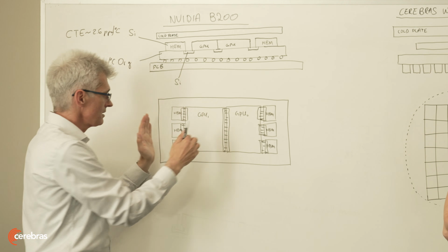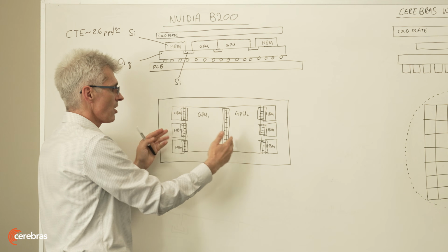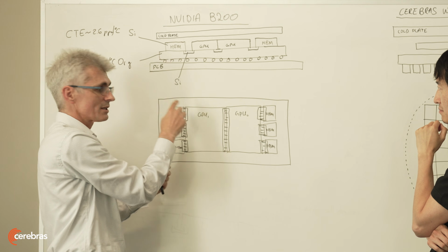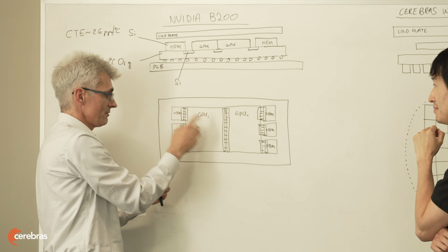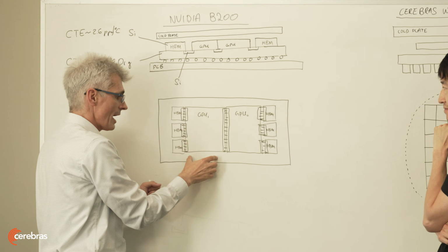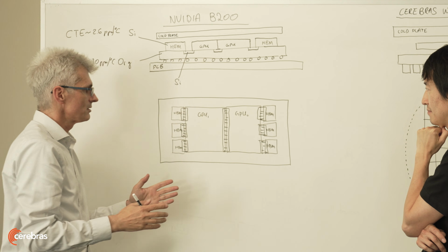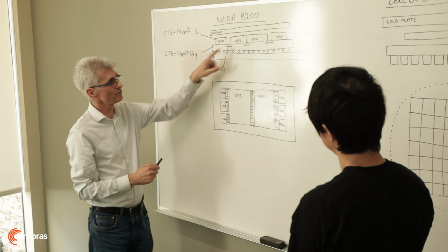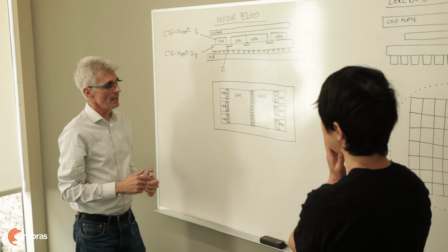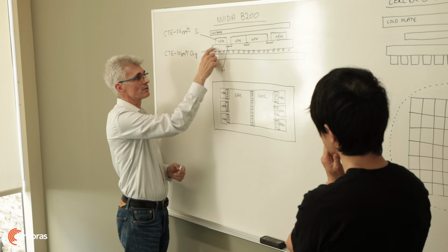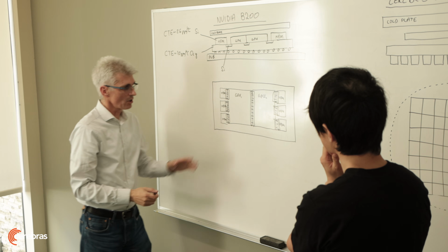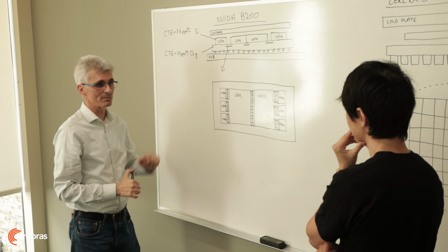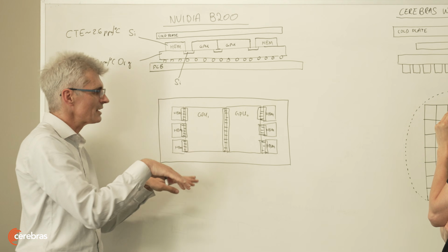So when initially they made this package structure on a large piece of silicon interposer, the coefficient of thermal expansion of both the logic die, the memory die, and the silicon interposer were matched. I see. So that's on H100. On H100. Okay. Then you go with a more advanced technique where you use bridges. In that case, you mix a silicon interposer with another type of material. It's a little harder to mitigate those differences of thermal expansion, either when you assemble or even after assembly.